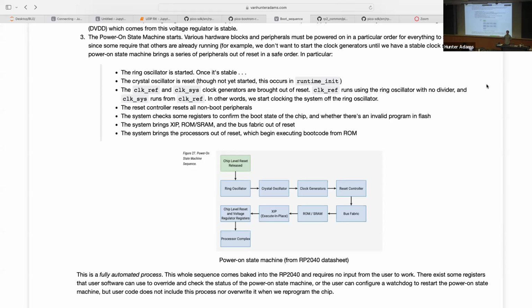So what that implies is the speed with which this ring oscillator clock is ticking depends upon the code that's being executed. It depends upon the temperature of the chip, and it depends upon the voltage that you're applying to the chip. That implies, for instance, that you might be running some program off the ring oscillator. It's running at some speed, and then you cool the system down and it will speed up. You increase the voltage that you apply to it and the system will speed up.